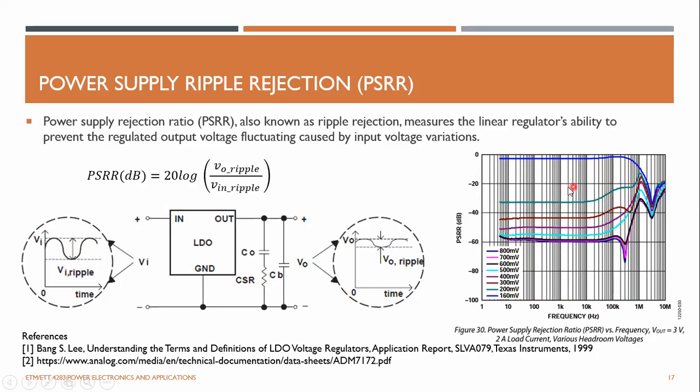Most of the time, when you buy a high PSRR regulator, you can eliminate any noise coming from the source side. The supply source is always noisy. By using a high PSRR linear regulator, you can keep your noise level to a very low value.